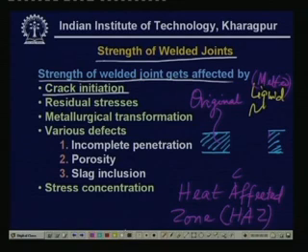That is, you see that whenever it cools, after cooling this kind of grains are formed, and when the solidification has ended, then there may be a place where a crack is formed. So, this is the part where a crack is formed. This is due to the solidification. There may be other causes of crack. For example, in this heat affected zone the crack may initiate. So these are the typical crack initiation processes.